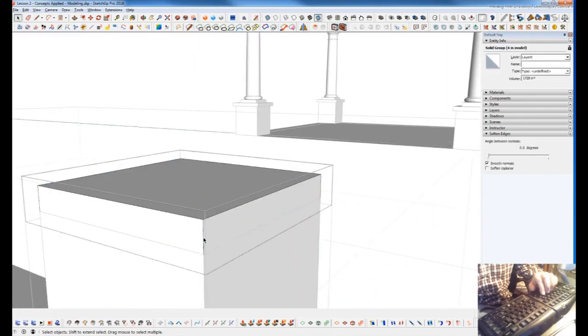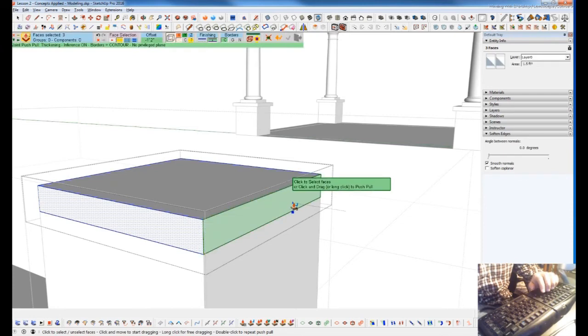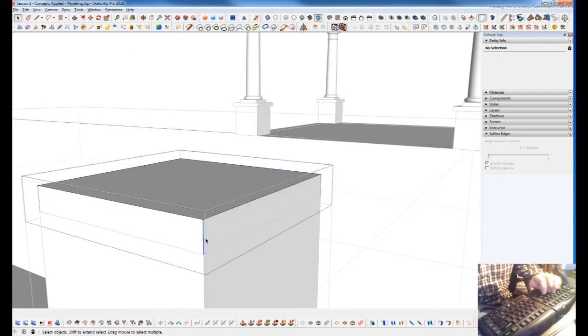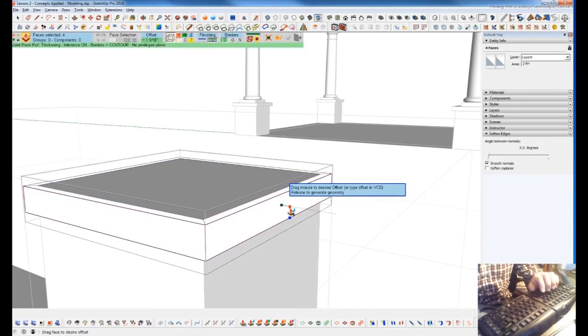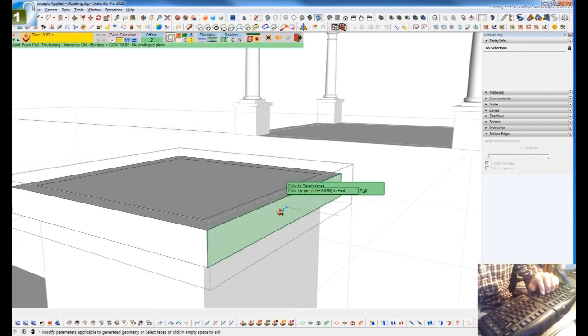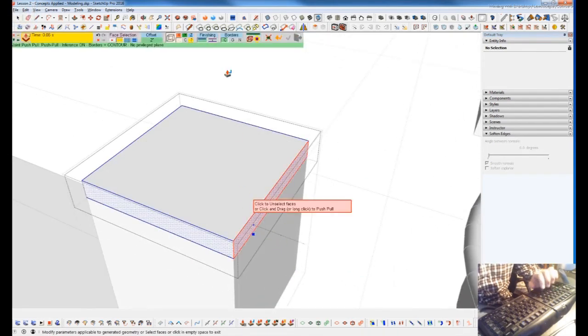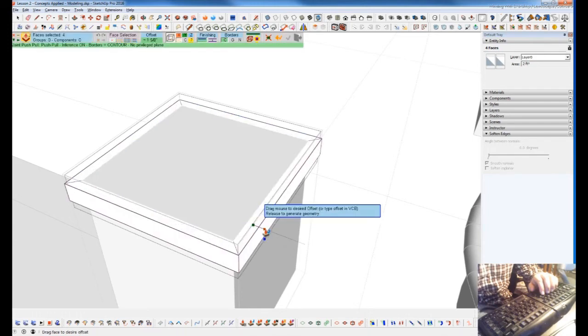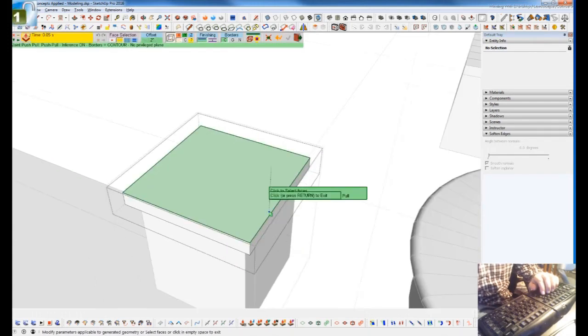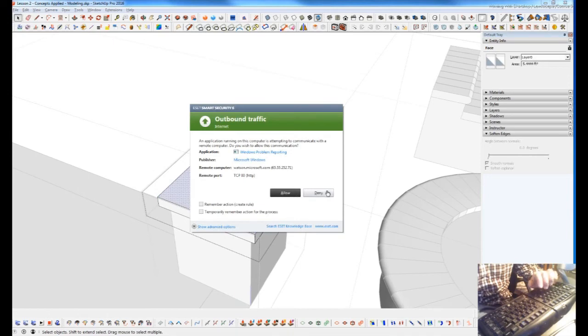Get inside here, grab that, and go select quad face loops. So grab that edge, use my shortcut, and I'm going to go to joint push pull and joint push pull that by 2 inches. But I have that set to thickening. I'm going to make sure that's not on thickening. Try that again to 2. There we go, and that should be good.